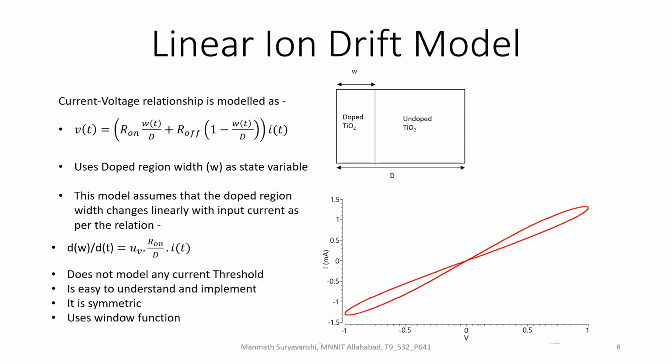This memristor model was excited by a 50 Hz sinusoidal voltage source of amplitude 1 volt. The resultant voltage versus current characteristic curve can be seen below the model diagram. The smooth curves observed in the characteristics indicate the linear dependence of current and voltage. Moreover, we can see that the lobes created by the positive and negative half cycle of the voltage source are identical, hinting at symmetric switching times from low resistance to high resistance and vice versa.